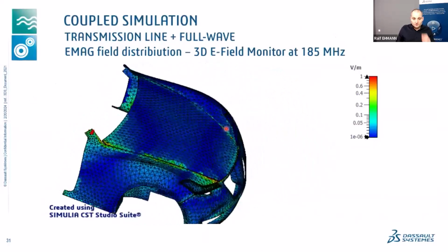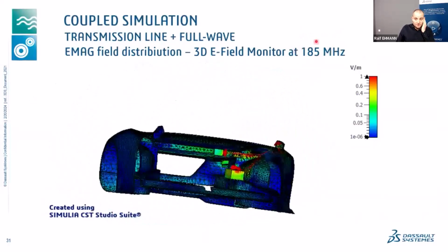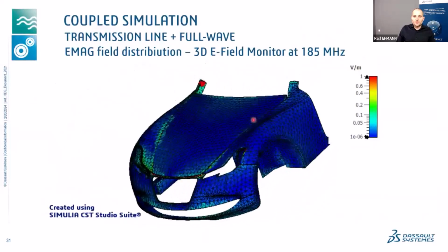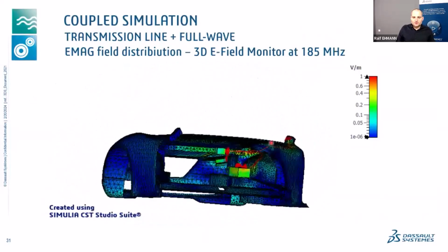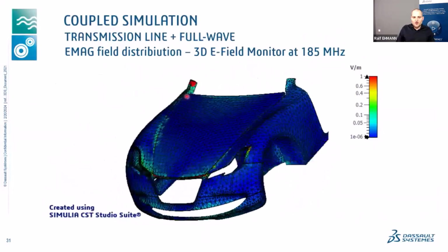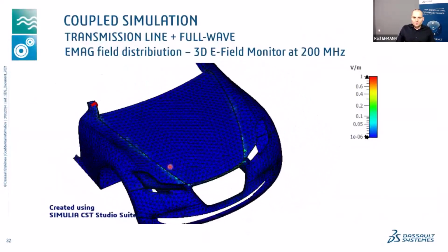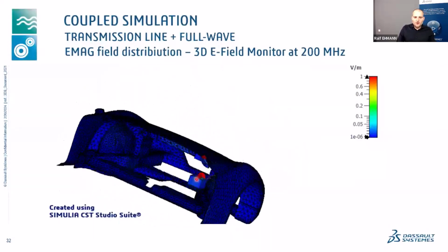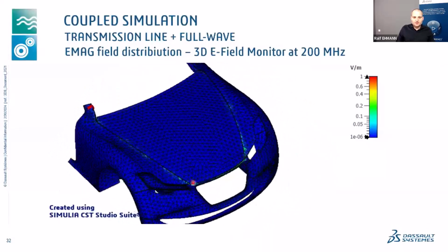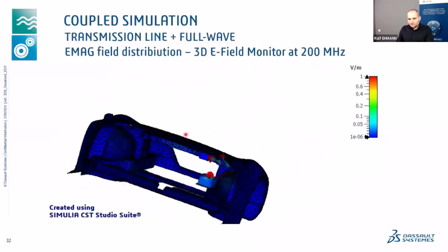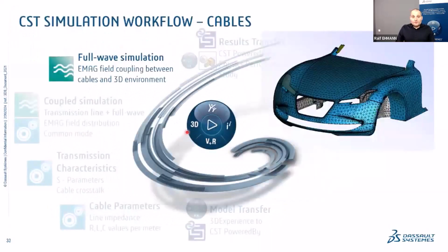At our particular frequency where the noise is quite big, we can see that it comes directly from the specific resonances of that cable harness setup. And then at 200 megahertz, where the system was much quieter, we are out of tune for these harness resonances. And okay, that finishes the simple setup of this simulation.